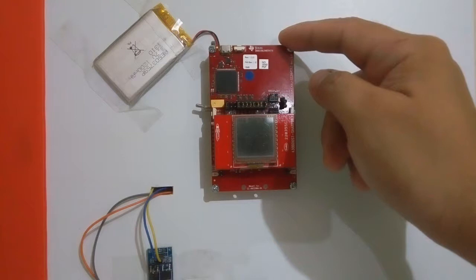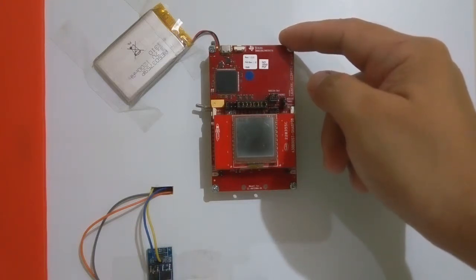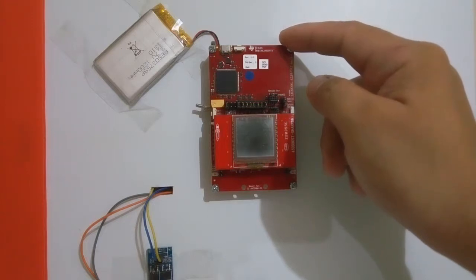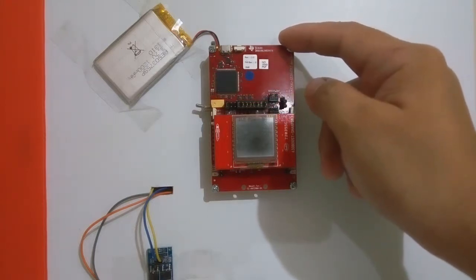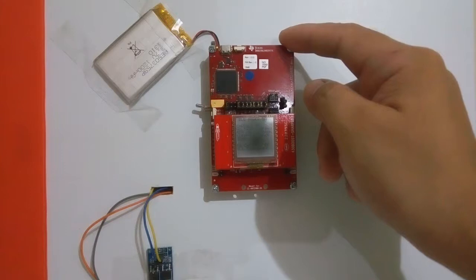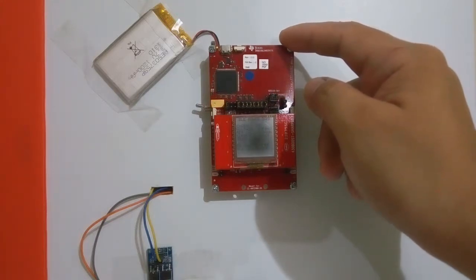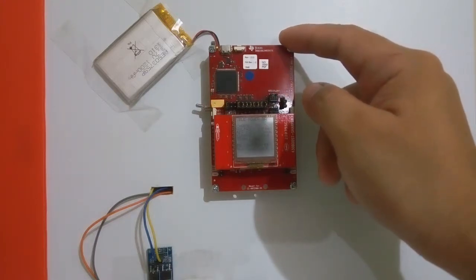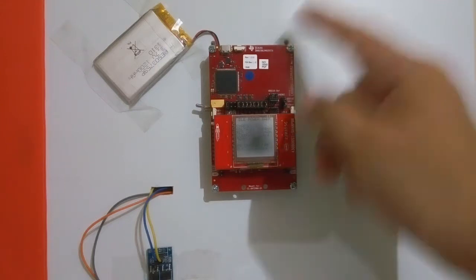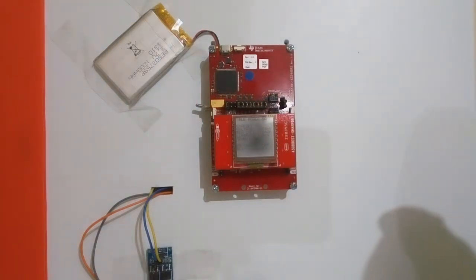Connected below the TI CC2640R2F launchpad is the Boost XL Backpack MK2, which has the BQ27441 fuel gauge and 3.7 volt 1200 mAh lithium polymer battery. The CC2640R2F MCU communicates with the BQ27441 fuel gauge using the I2C interface to read the state of charge, remaining capacity, voltage, and others.